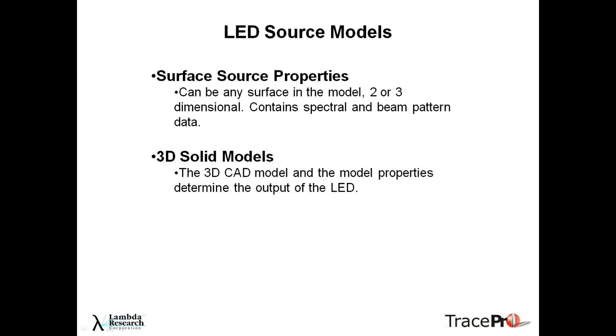And then the last would be 3D solid models. These would be creating an accurate CAD model of the LED or the source, adding in all the appropriate model properties, surface properties, material properties, fluorescence properties, and then actually letting the model itself determine the ray pattern, so that the geometry and the structure of the source determines what happens with the output.